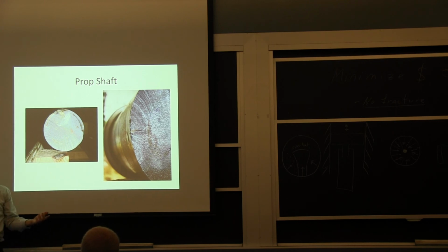So it wasn't what I call an overload case, because with half of the section and all the stress intensity, everything that's associated with having a crack in the material, you were still holding on and operating. It's a little vicious because unless you inspect, everything goes well until you reach the fracture toughness of the material and you have a fracture.